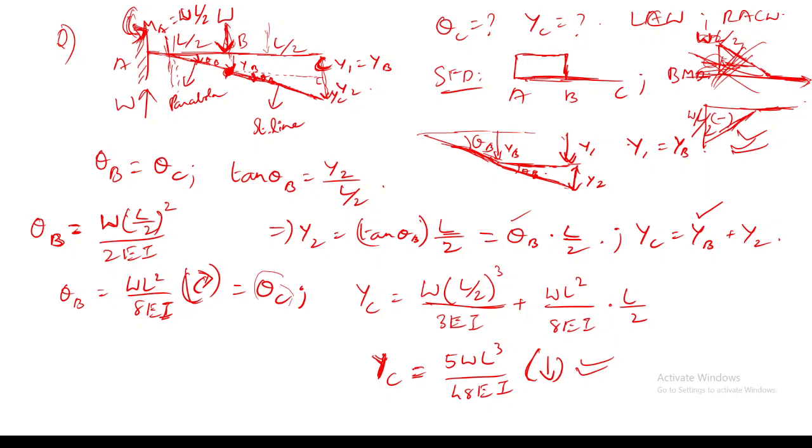Okay, sir. See, this left clockwise and right anti-clockwise is applied for every kind of beam. Left clockwise means positive, right anti-clockwise is also positive.